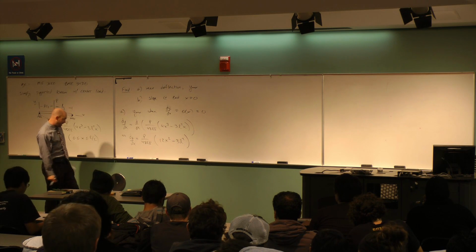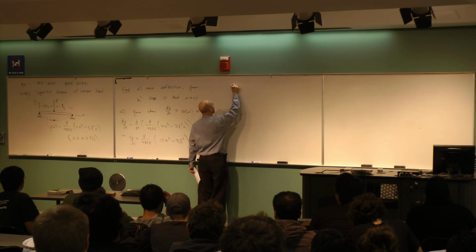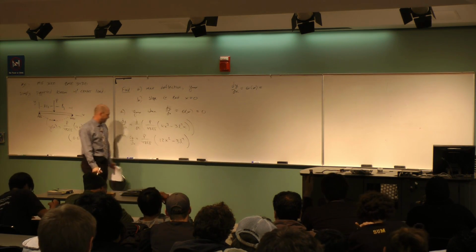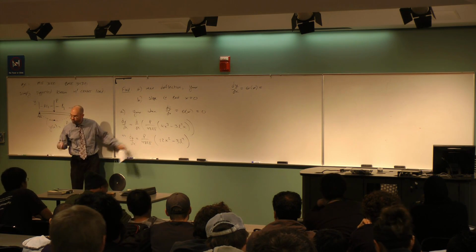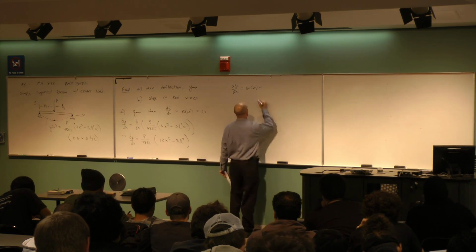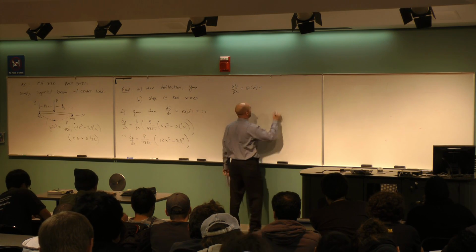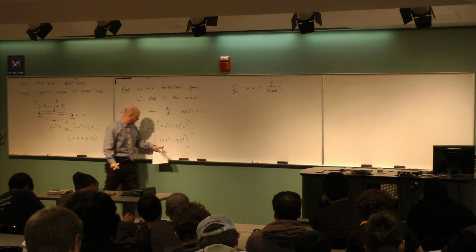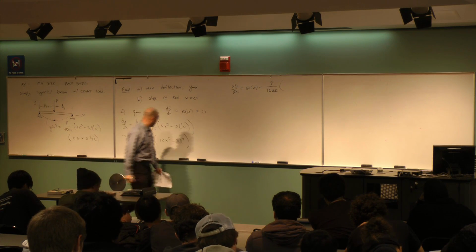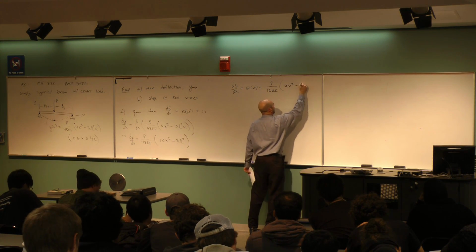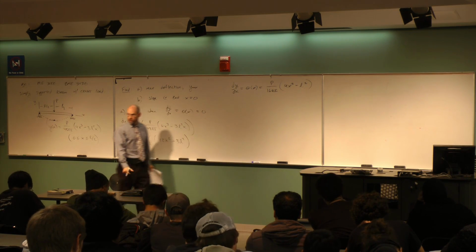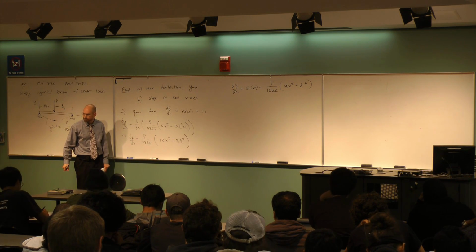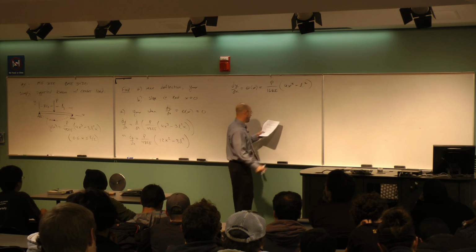And so the question is, can I simplify that at all? I can pull a 3 out of there, right? So if I pull out a 3, I'll have 3 over 48, which is how much? 1 over 16. So I'll have P over 16EI. I've pulled a 3 out. And if I pull a 3 out, how much do I have in the first term there? I'm going to have 4x squared, right? And I'll have minus L squared right there. Everybody good with that algebra? Just factored a 3 right out, canceled the 48, made it a 16. All right, so that's dy/dx right there.